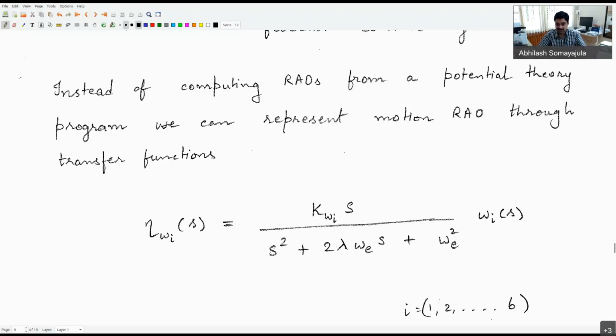Okay, this does not represent reality. Let us be very clear. If you really wanted to represent reality, you need to use whatever you did in your statics and dynamics or ship motions course. You have to find the RAO properly and then figure out what the motion is for the given wave elevation from a spectrum. But here I am taking a shortcut because my objective is to have a representative signal which looks like it, but I'm not interested in getting it exactly right. My objective is to test whether my control system can deal with signals which look like that, rather than seeing exactly how it deals. It's for testing purposes. Is everybody understanding what I'm trying to say? Yes, sir. Yes, okay, good.